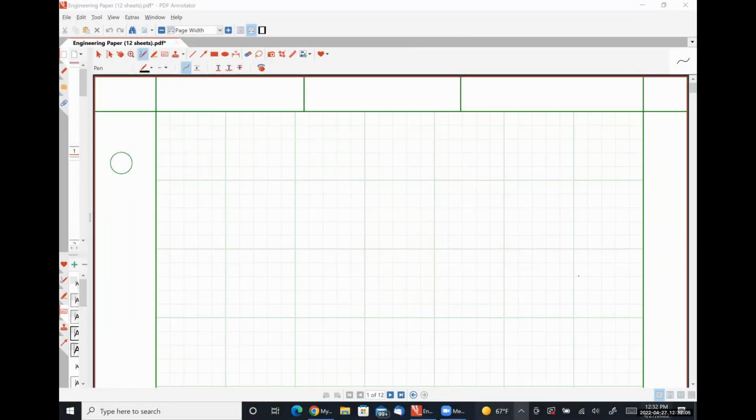Today, we are going to talk about the frequency response of cascode amplifiers. And we are going to constrain our investigation to high frequency, because cascodes are typically implemented as an integrated circuit, and so it's going to be the parasitic capacitances that are going to overwhelmingly affect the behavior.